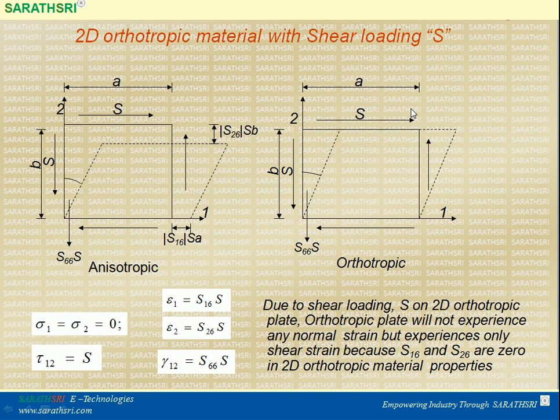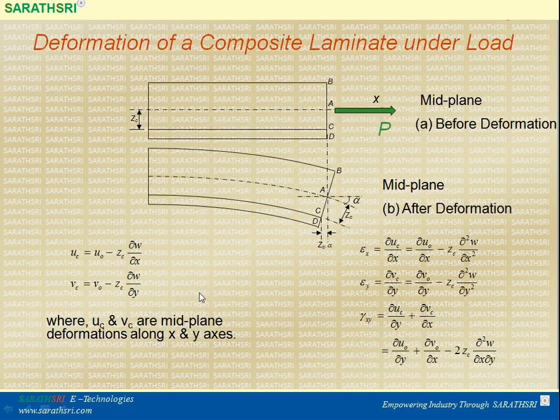Similarly, if it is subjected to shear loading, what kind of behavior does it show? Because of shear loading, this will induce only a shear strain and doesn't induce any normal strain, because these components become zero in the flexibility matrix.